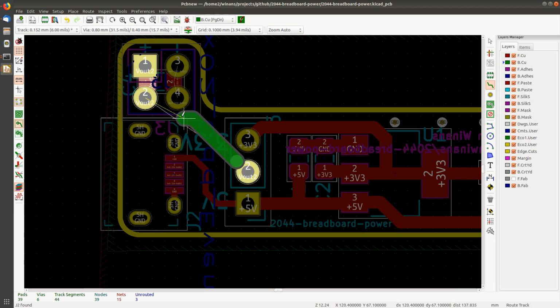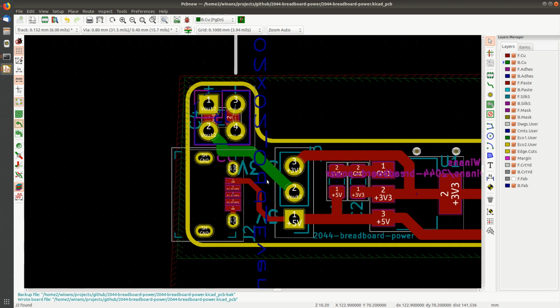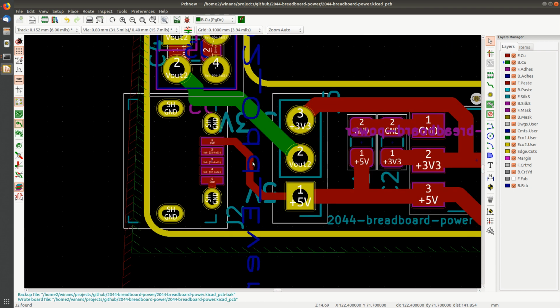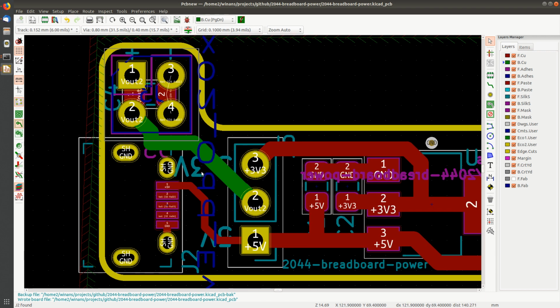All right. It's okay to be underneath the connector that's on the top. There's nothing down there to mess up the track on the bottom layer. Of course, on the bottom layer now, we've disrupted the ability to use it as a ground plane.